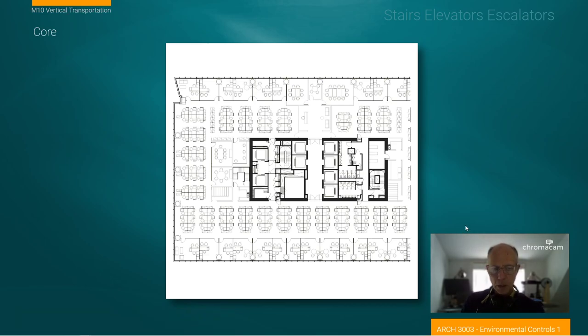Maybe a way that this graphic will help to describe for you. So here we have a multi-story building. We're looking at a floor plan. This could be any floor plan of the building. We're looking at a glazing system with outside offices, just to help you get oriented here. And we have these two darkened areas, which are considered the core of a skyscraper. They perform the horizontal shear of the building to give it stiffness as it rises up multi-stories. And it's also the place then typically that is fire protected and safe to perform egress.